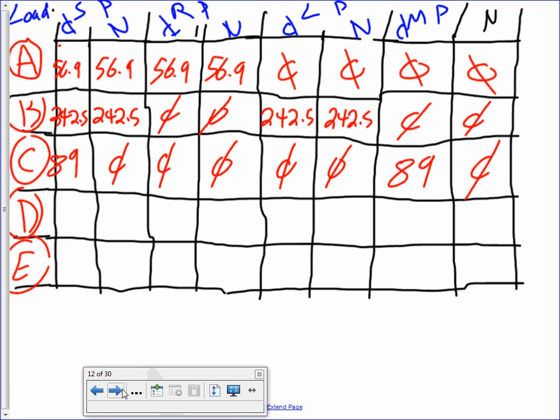So I'm going to go back here. For D, there were 70 here. All of them are three-phase. What do you think I should put under the neutral? Big fat zero. They don't contribute. Will they be fed from the receptacle panel? I hope not. These are going to be motors from the mechanical panel.